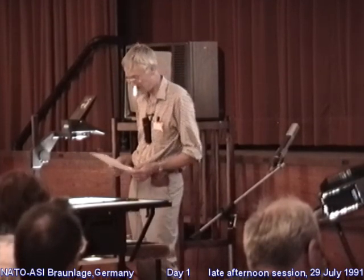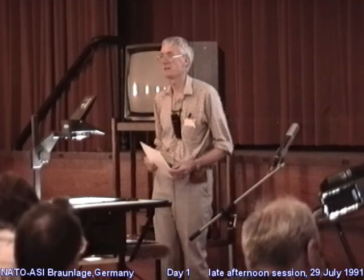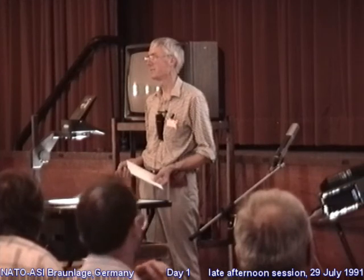Another type of evidence is in connection with the kind of experiments that we've been doing at Lancaster for some time, taking an ultra-high vacuum apparatus and doing a micro-contact experiment under conditions where we can obtain single asperity contact to get around the problem of contact between extended rough surfaces.